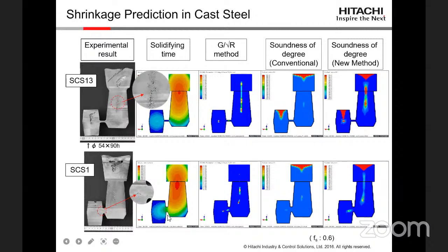You can check near the ingate the temperature is higher. So there is minor shrinkage available in the casting according to the cut section. Here we can correlate and predict all these defects in the casting before going to the shop floor.